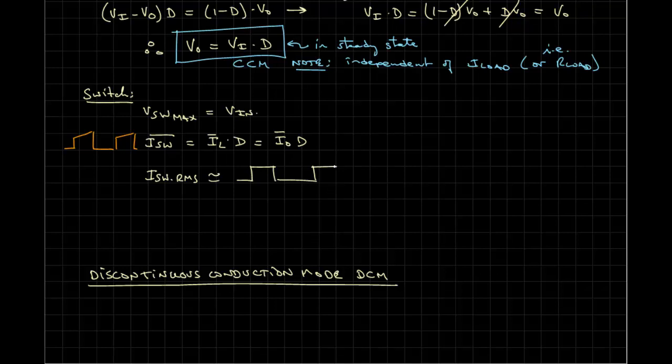The first way is we assume that we have a square current like this that has a value IL or Io during this period of time, and it has this conduction of D and 1 minus D. This would be where we'd be plotting t over Ts, normalized time. So this is a simple RMS calculation. It's the amplitude times the square root of the duty cycle.